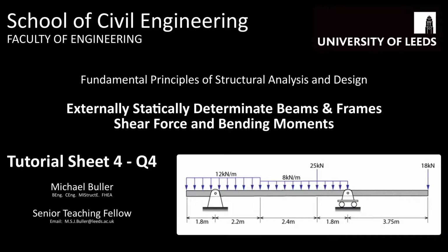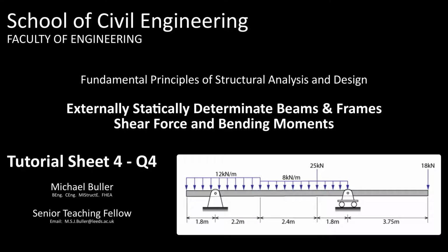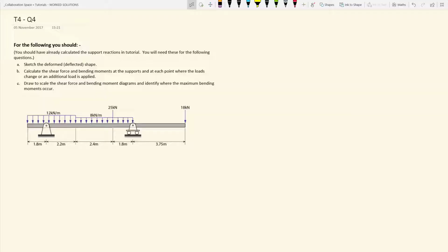Hello, my name is Mike Buller, and this video explores some of the fundamental principles relating to structural analysis and design. This video will consider a simply supported beam with a cantilever both to the left and the right, and demonstrate how to calculate the shear force and bending moments associated with the imposed load. It will also demonstrate how to draw the associated shear force and bending moment diagrams.